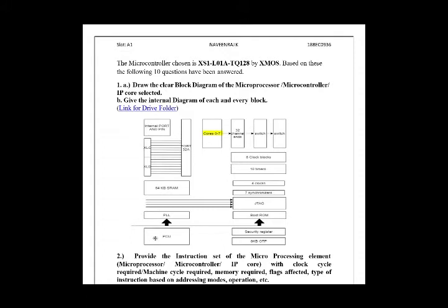This is the PLL. The PLL creates a high-speed clock that is used for the switch, links, and reference clock. The PLL multiplication value is selected through the two mode pins. There are two mode pins that will select this, and it can be changed by software to speed up the tile or use less power. So this consumes power because a high-speed clock is being set, right? So this can be changed using the programs. By default, it has some value.